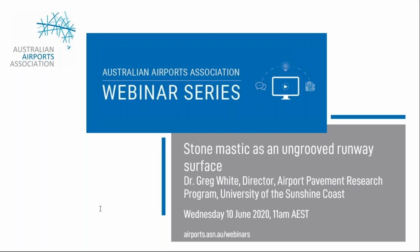Well, we know that oxidization and stiffening is really only occurring in the top 5 to 10 millimeters of the surface. So I would imagine that profile would be very similar for dense graded and for stone mastic. I don't think the stiffening over time would be substantially different, just because it's stone mastic and it's got a bit more bitumen in it, about 10% more, I suppose. So an extra 0.5%.